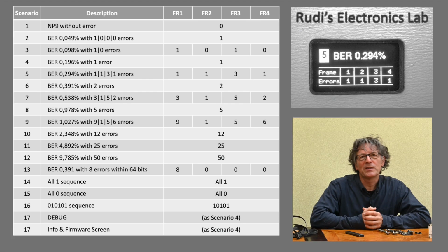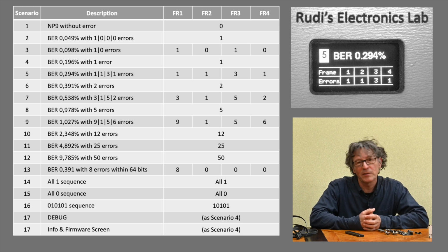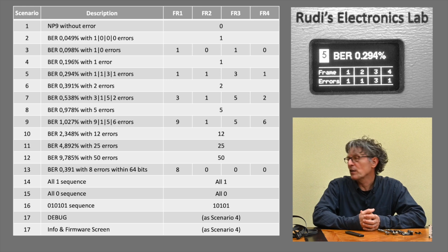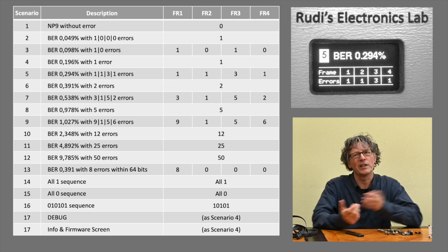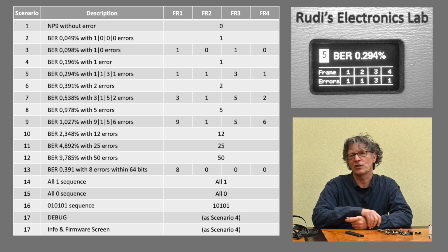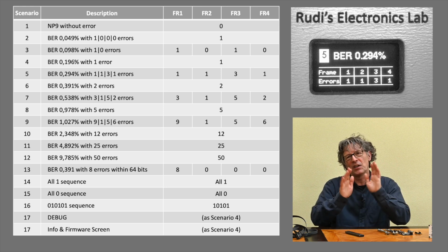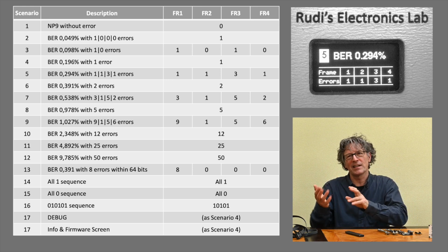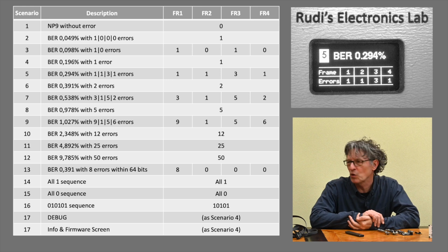Now, also showing you a little bit of the different scenarios. I already talked about different scenarios that you can select for bit error testing. These scenarios can have built-in errors at predetermined conditions. I just decided myself where the errors are. I made a table and I said, okay, I want to have an error at the 175th bit or so that comes along for a certain pattern, etc. So there are 16, 17 values that you can browse through via the scenario interface, and the first 12, 13 or so are regular scenarios.